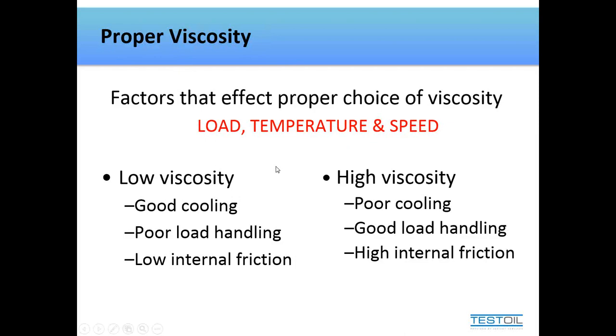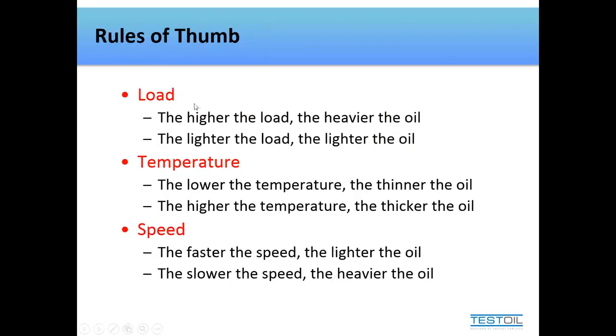So if you're choosing an oil for especially a custom application, you want to get somewhere in between here, between high and low viscosity. Just to give you an idea, a turbine engine will be a 32 viscosity. High speed, low load, can generate a lot of heat. High viscosity would be a gear oil. Large, slow-moving gears, a lot of contact, a lot of load. So you can use that as a basic rule of thumb.